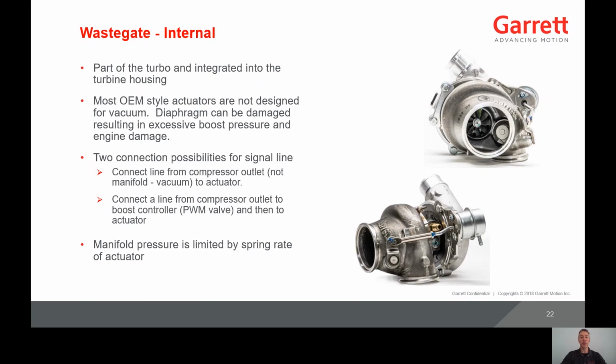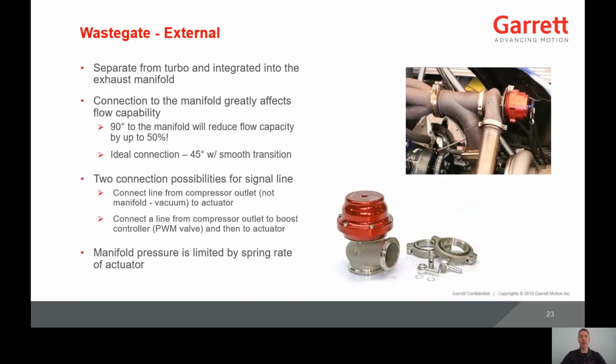So if using a boost controller and you still cannot increase the peak boost pressure, most likely an actuator with a stiffer spring will be required. The external wastegate is separate from the turbo and integrated into the exhaust.